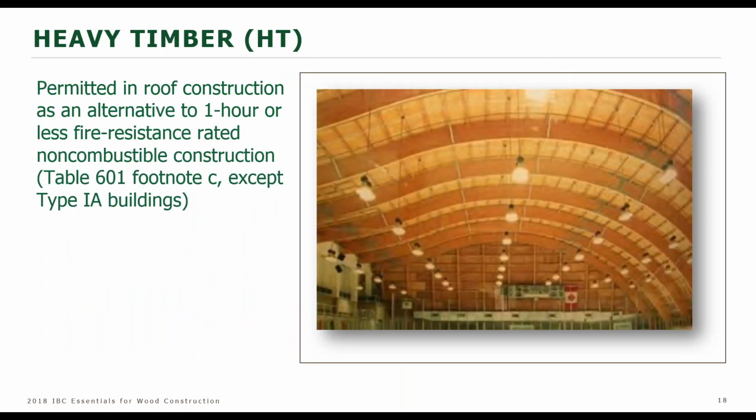Heavy timber has a unique place among the construction types, especially in roof construction. If you go to table 601 and look under the row for roof construction, you'll see a footnote C. Everything except type 1A, the largest, tallest buildings, every other construction type can have a heavy timber roof structure.